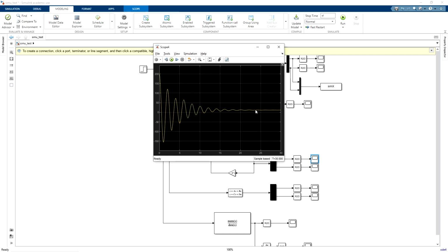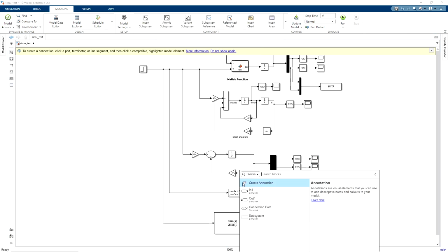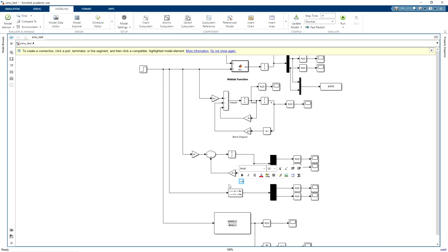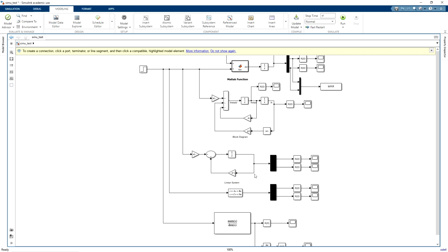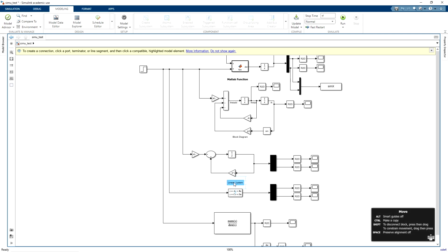So this happened because we removed the nonlinear term, sine of angle. So this is a linear equation, a linear system. As I mentioned in the note earlier, for small angles the linear approximation is correct. So linear approximation is only valid for small angles. Now this 200 degrees is obviously a huge angle. The simulation is not able to rightly predict that it is indeed going further.